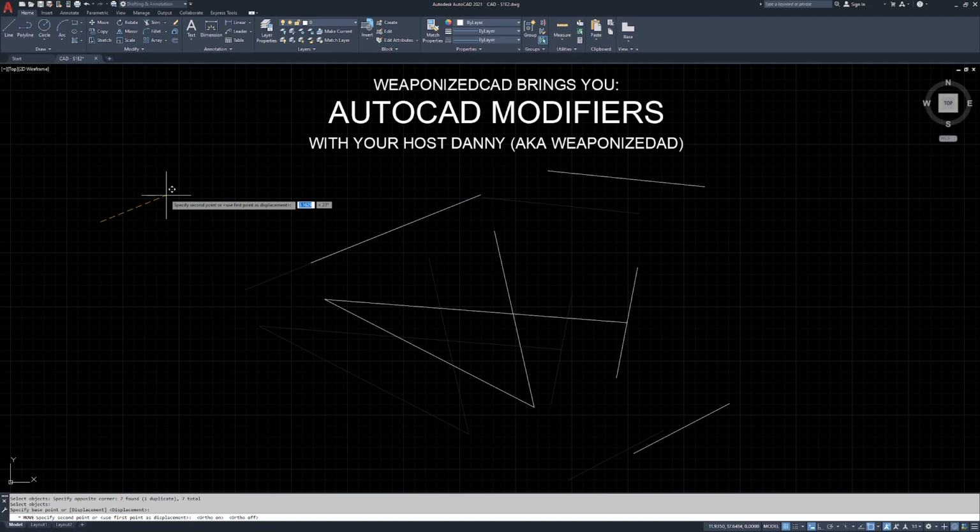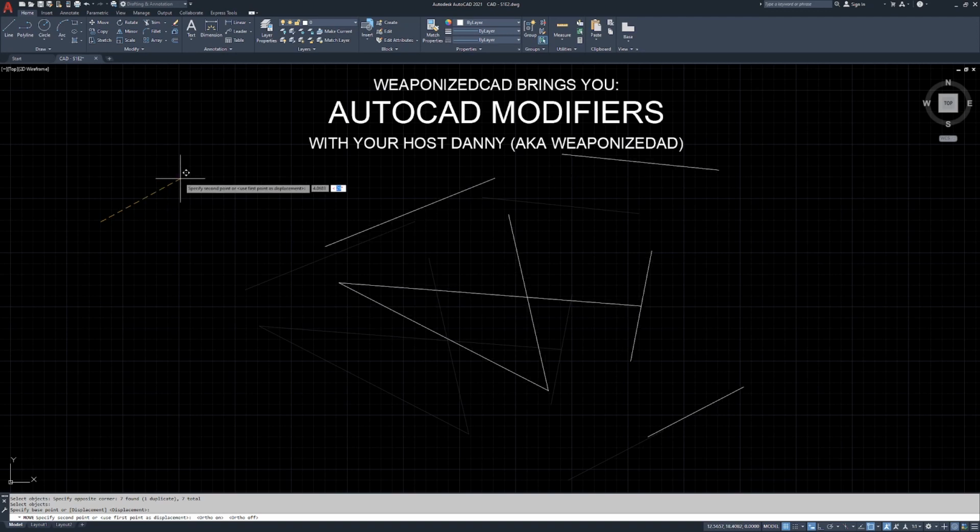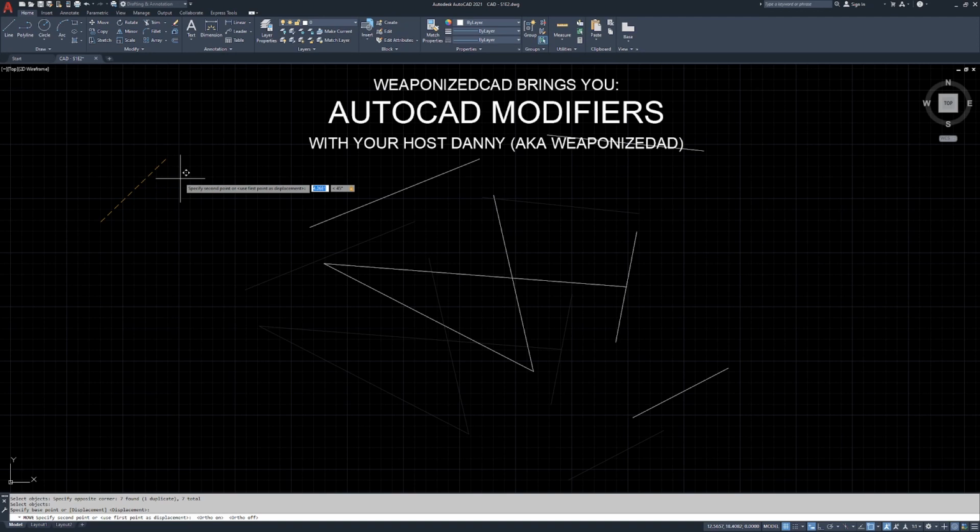If you hit the tab button, you can actually type a degree in there, the actual angle that you want to move it. So let's move it 45, and then let's hit tab again, and now you'll notice that my cursor, the orange dashed line, is locked at 45 degrees, and there's actually a little lock symbol on the 45 degrees that we just keyed in.